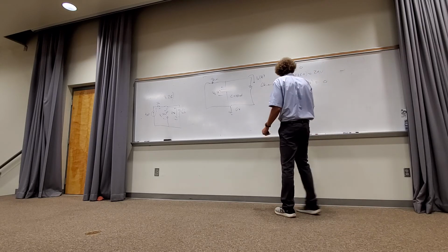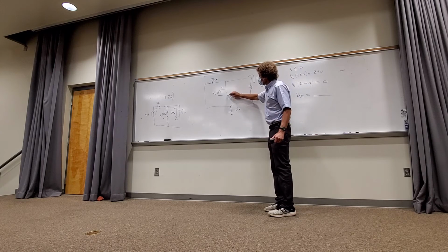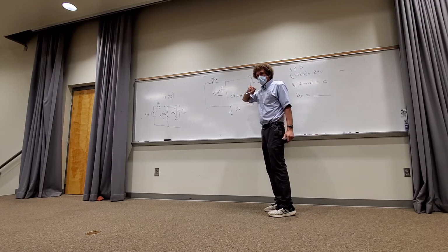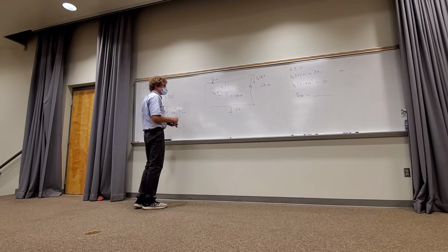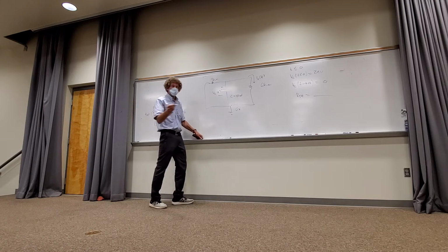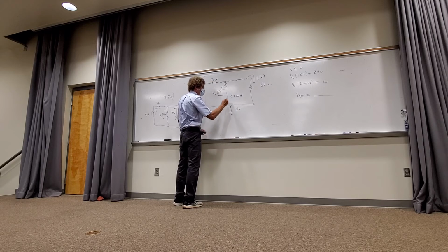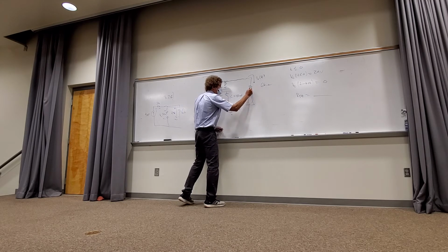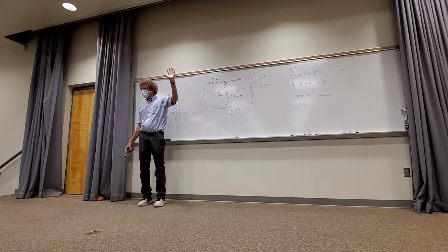R Thevenin. What's R Thevenin going to be and why? It's the Thevenin equivalent resistance across those two terminals, right? So sometimes this helps people. If you want to know what's across those two terminals, just take a black marker to the top, take a different color on the bottom, and if those encompass everything that's left, anything that's got black and purple on either side is in parallel. You all see that? That's a simple way of figuring out what's in parallel. You all see they're in parallel.